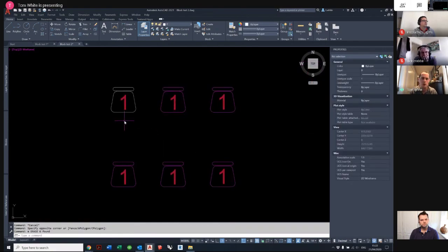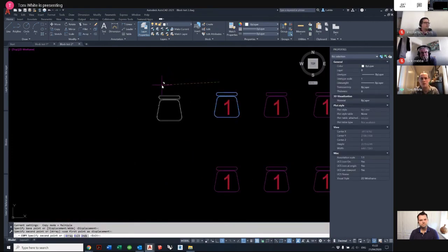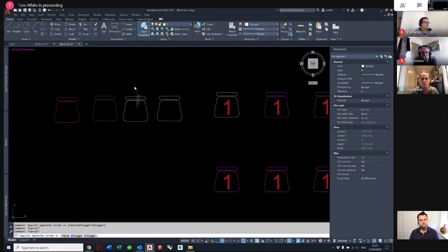So that's the reason why I try my best, if possible, when receiving a drawing, to use set by layer, which is hugely useful, but I suppose it can be relatively dangerous because somebody has spent a long time producing quite a nice drawing. And in this circumstance, they have what they have helpfully done.